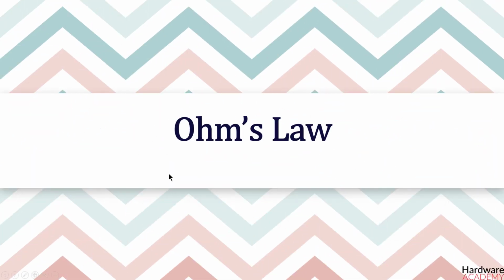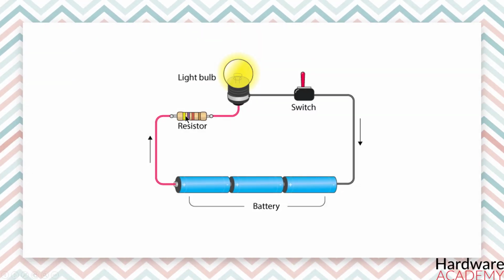Alright, so in the previous course we talked about resistors, and now we know that resistors are used to limit the current in a circuit, right? So let's imagine that we have this circuit and the light bulb requires 1 ampere in order to fully glow. We also have a power supply of 5 volts, and the question is, what value of the resistor should we use in the circuit in order to set 1 ampere of current to flow in the circuit?